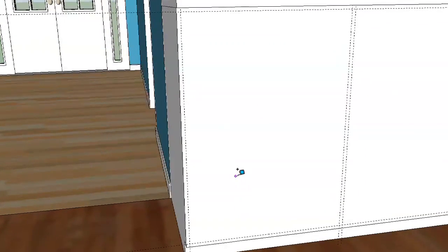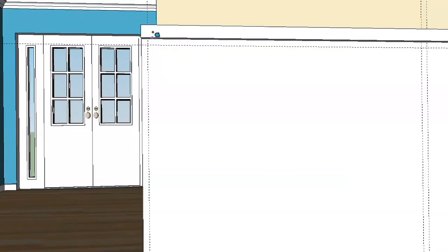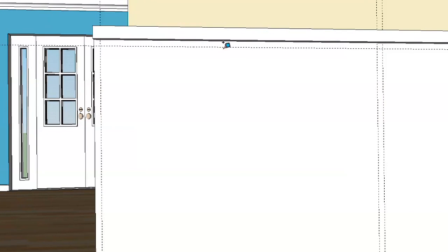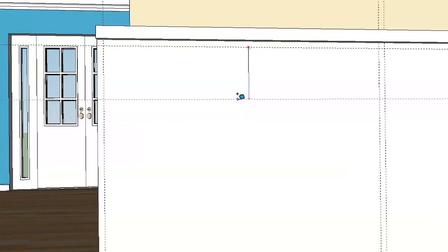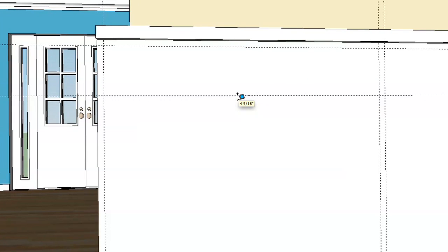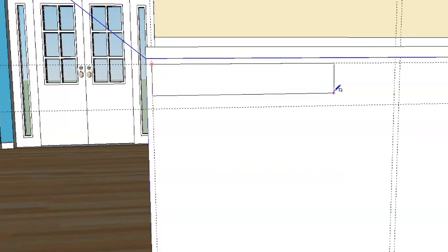So that's the amount of space that I want to keep clear. And then the next thing, I want to mark out where my drawer is going to be. The drawer is going to start at these guidelines here, right? Just like the door, we want space at the top. But I'm going to have the drawer come down maybe, let's have it be 4 inches. Okay, so in fact, I'll go ahead and draw, remember, our cabinets are grouped, so I can draw the doors on top of them without any worry. Draw a rectangle right there. Okay, so that's going to be our drawer.